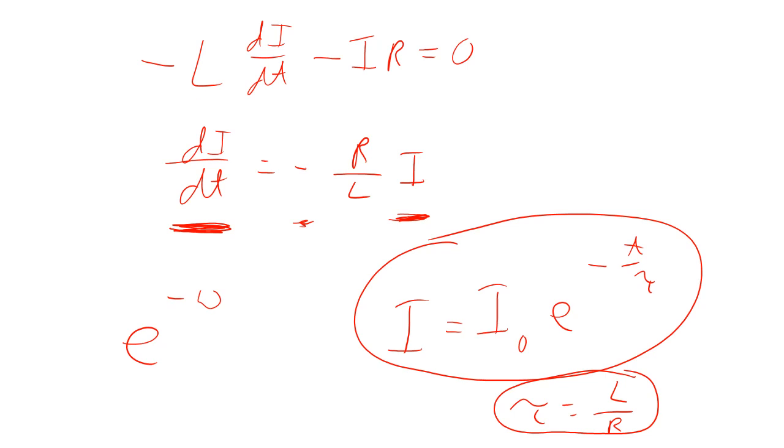It's losing the energy, so if you were to make a graph of current versus time, it would start off at I naught. I naught is whatever the current was initially when you threw the switch, and it's going to start dropping. It's not going to drop instantaneously. It'll drop pretty quickly, but it will not be instantaneous. That's why anytime you have an electric motor or something and you suddenly unplug it, it will try to keep the current flowing, and you can actually build up quite a lot of charge.